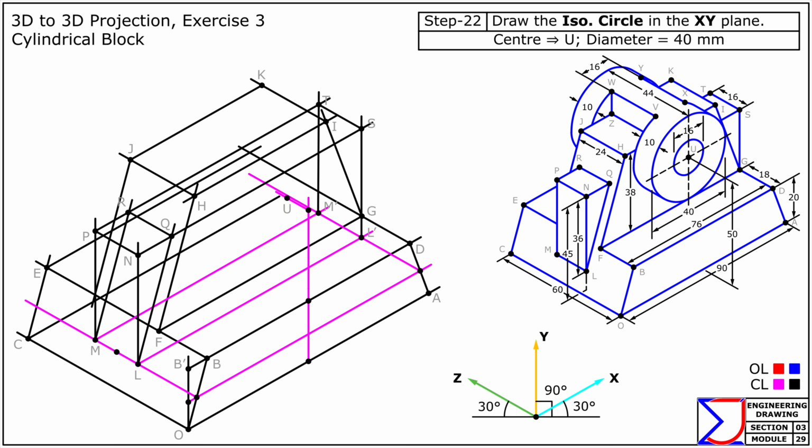To construct a circle with a radius of 40 mm in the isometric plane and copy it to the respective positions, apply the technique we learned in modules 25 and 26, isometric views of planes and isometric views of solids.